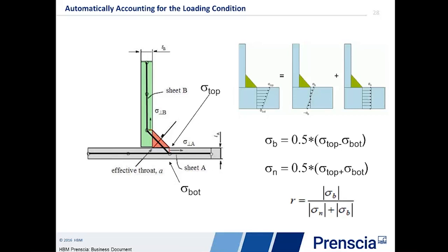Here we have a stress recovery approach that allows us to calculate not only the hotspot stress, but maybe the stress below at the opposite surface or the bending ratio. We're able to take those stresses and compute how much of the stress is caused by a tension load and how much of that stress is caused by a bending load.